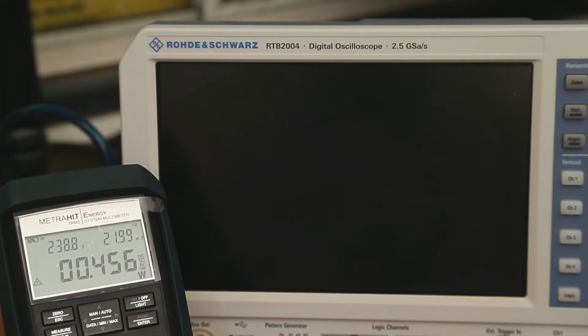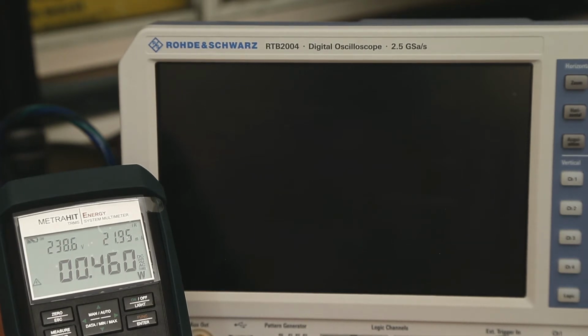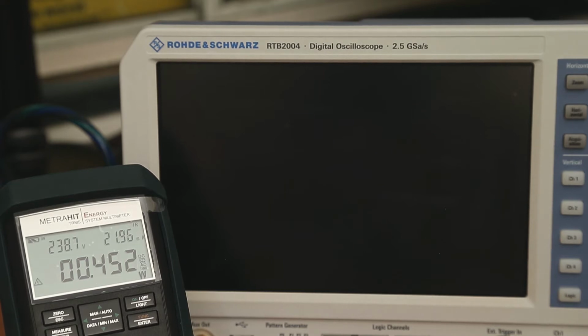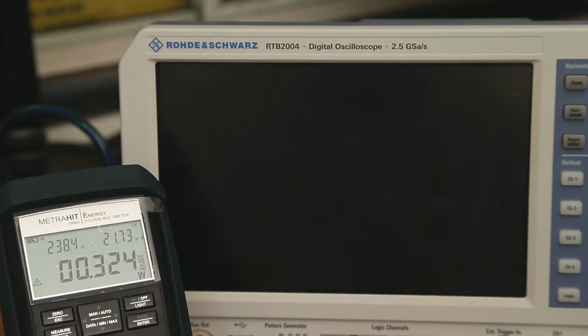One thing that is worth stating on the Rohde & Schwarz, which I forgot to mention previously, is that when you've set everything up to take a signal, and you might have put the time base in, set the channels up to certain volts per division, etc., when you switch it into standby mode, it remembers it, which is a real pleasure, because I might set something up at night time, decide that I want to have a look at it tomorrow morning,